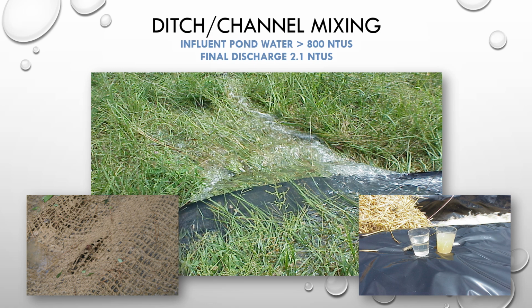This final discharge, after running through that grassy area, was in the single digits. And again, as I mentioned before, we're usually aiming somewhere around 20, which is also very clear water in terms of turbidity. We're usually looking at upwards of 95% turbidity removal when we're hitting all those important components.